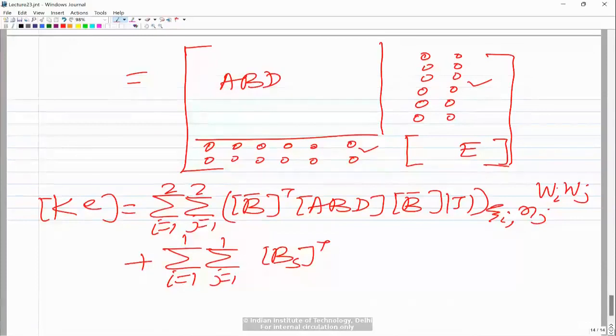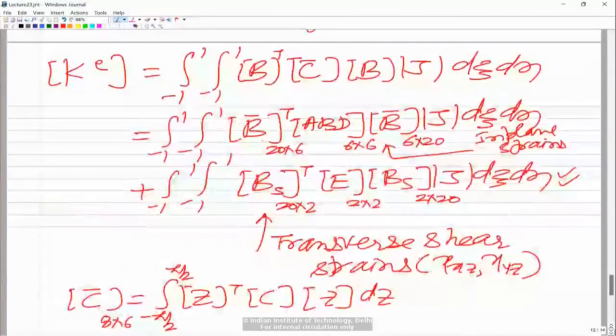So what we are doing actually, because when this element is used for thin plate problems, it leads to shear locking. That means if we use full integration, the stiffness is overestimated. This over stiffening is coming from the transverse shear part. So to reduce the stiffness, we are under integrating this transverse shear stiffness part.